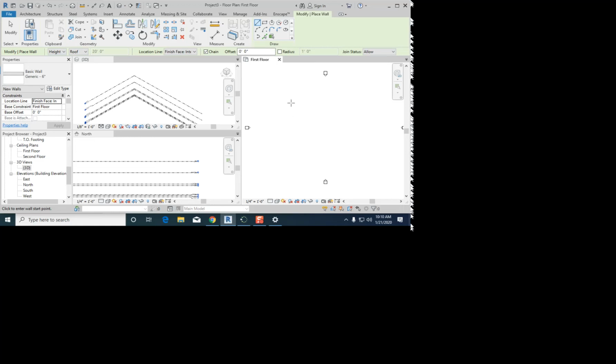Let's come here and let's draw our 15 feet. So look at my screen for just a minute. If you haven't drawn in any kind of CAD before, this might take you a sec. But you click and then you drag and it tells you how far you're going. But instead of trying to figure out where 15 feet is, just type in 15, enter. Revit thinks in feet. So 15 is feet, okay? And then I'm going to pull my mouse down, 15, enter.